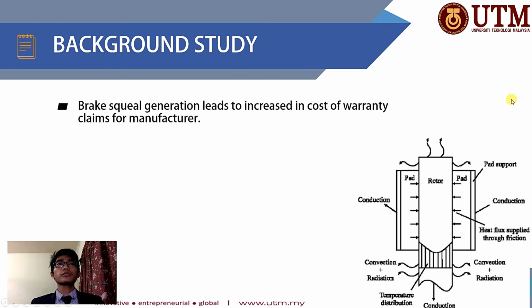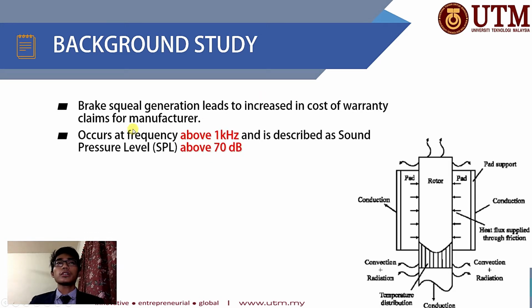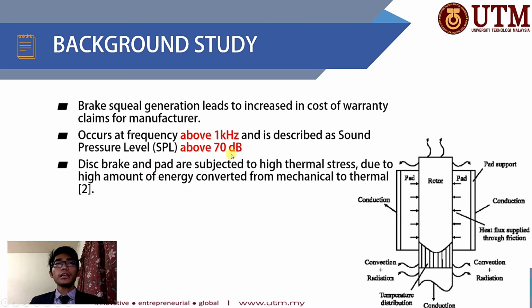For the background study, brake squeal generation leads to increase in cost and warranty claims for manufacturers. Brake squeals always occur at a frequency above 1 kHz and are described as sound pressure level above 70 decibels. And disc brake and pads are subjected to high thermal stress due to high amount of energy converted from mechanical to thermal. This is the example of a figure where the heat is dissipated from the disc brake.